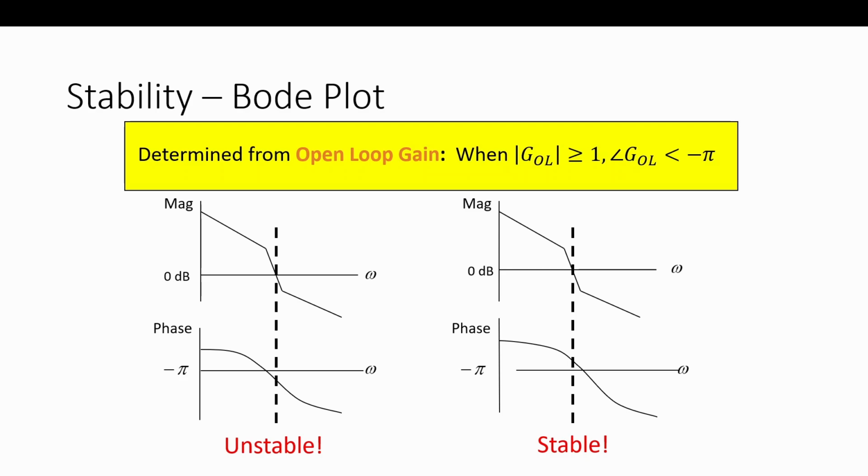We can just go in the lab or go into our simulation and create this plot if it's stable. Just come in from one node, look at the output, and figure out what is its magnitude and phase as we sweep frequency. So we don't have to do any math. We could just go right to our system if we have our hands on it, meaning if the simulations aren't done or if it's working down in the lab, and get this Bode plot. Which, by the way, we can then model and figure out for transcendental systems, which may not come to simple poles and zeros, things like that. We can figure out the same stability, like time delays, for example. Forward gains.